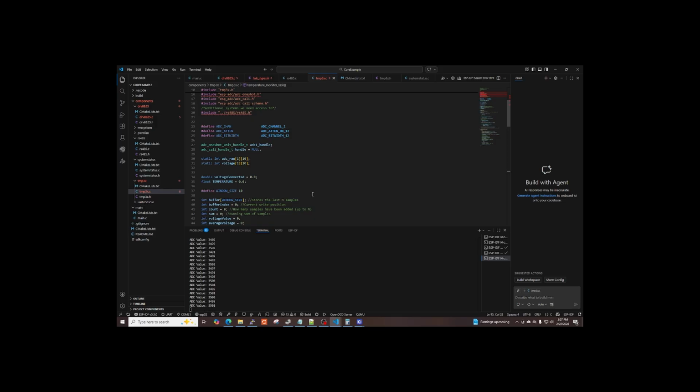So that's what we'll do in the next video. The next stream is we're going to troubleshoot this. And I think what we're going to have to do then is just find a configuration that works and do some updates to the PCB and do the version 2 spin a little sooner than I anticipated, because we can't really do a whole lot without actually running the motor and doing all this at the same time. We need the ADC to work. This was definitely a problem that was unforeseen because the documentation is not clear. It only mentioned it down the road about Wi-Fi interference, and I should have looked for that.